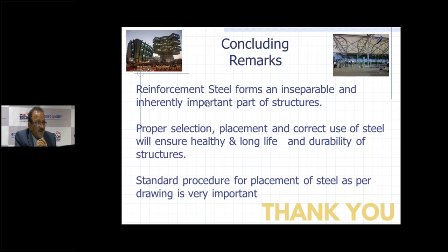This fly ash makes concrete more dense, because the secondary hydration will reduce the permeability and the voids in the concrete, and thereby the ingress of moisture inside the concrete gets restricted, and thereby the steel gets protected from corrosion. So there is an indirect benefit of Portland pozzolana cement in preventing corrosion. There is no direct correlation, but yes, some cement companies, I will not name them here, call their cement corrosion resisting cement, but that is actually nothing but Portland pozzolana cement.